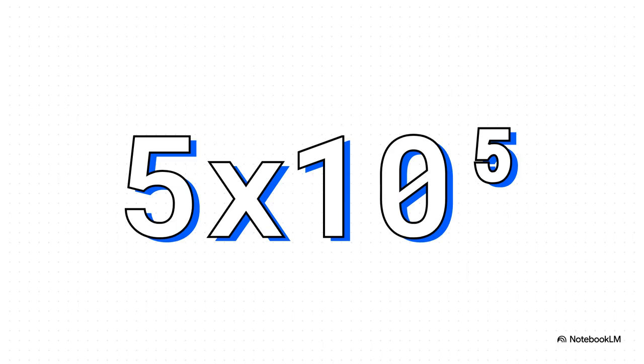You can think of it as a cosmic tug of war. On one side is the fluid's own internal stickiness, its viscosity, which wants to keep everything smooth. On the other side is the fluid's momentum, its speed and energy, which is trying to tear it all apart. The Reynolds number is just the score in that battle. And for flow over something like a flat plate, once that score hits about 500,000, momentum wins. The flow just can't hold it together anymore, and it trips from smooth laminar into chaotic turbulence. It is a fundamental tipping point in how fluids behave.